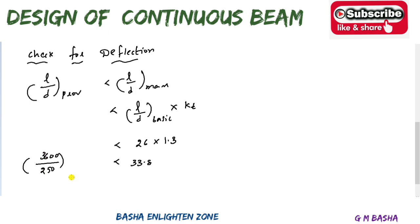So it will be 14.4 and the maximum will be 33.8. So l by d provided is lesser than the l by d maximum, so we are on the safe side. Therefore, the check for deflection is also safe. So check for deflection is safe. Okay, so this is the way you have to check the deflection.